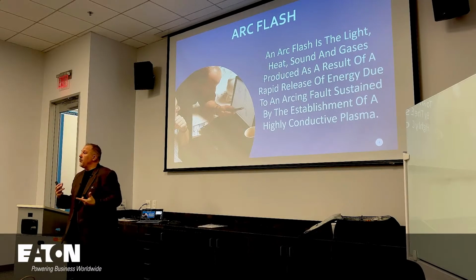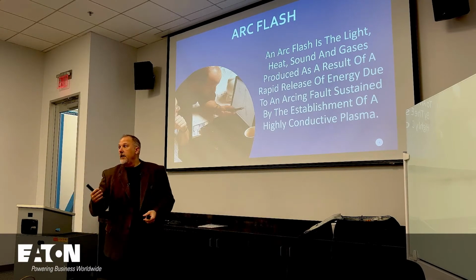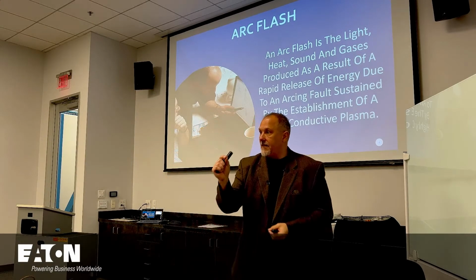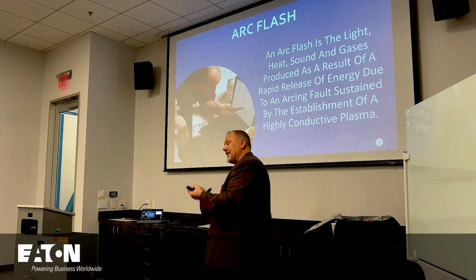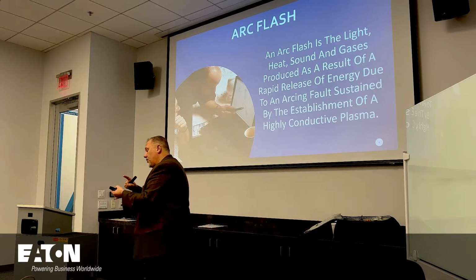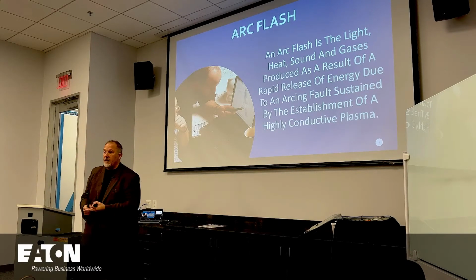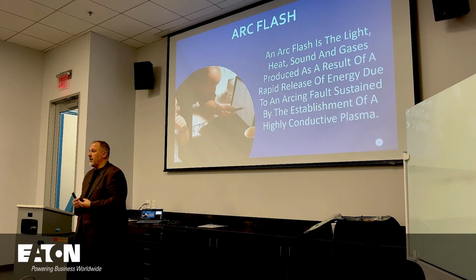You've got shrapnel. You've got pressure. We have IEEE 1584 that helps us calculate energy, heat only. IEEE 1584 doesn't tell you what the sound is going to be, doesn't tell you what the pressure will be, doesn't tell you how much shrapnel is going to come off of the equipment and subject the electrical worker to that violent event.